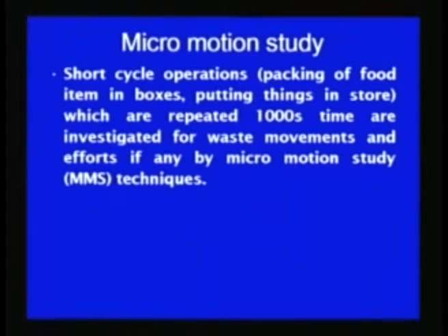So, for investigating whether any irrelevant, unnecessary movement is taking place while carrying out these short cycled activities or not, systematic investigation using the micro motion study technique can be carried out. So, for short cycle operations, the micro motion study technique is mainly used.